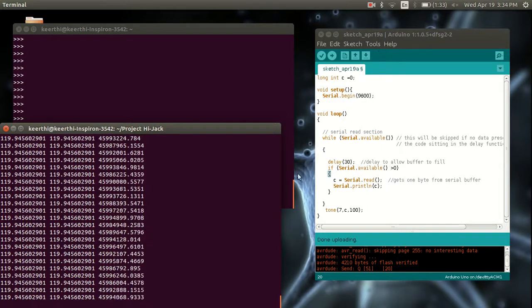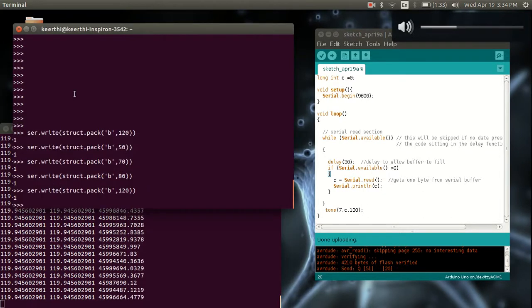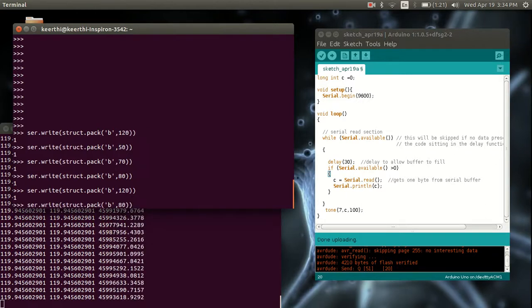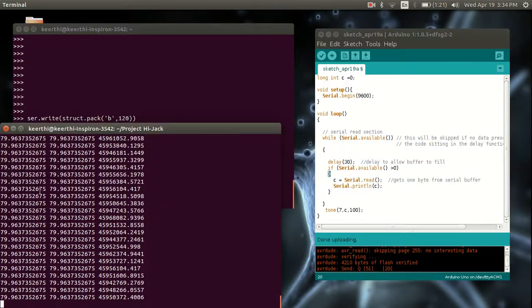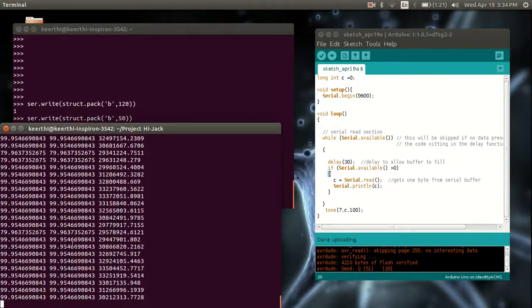Okay, I just paused to open up the FFT app, and you can see that this is printing out 119.95. It's just 120 Hz, so it is giving out 120 Hz. Now say you want to change it, you want to go to 80, and if you want to set that, just click on that and then bam, changed to 80 Hz. Now 90, if you want to give 90, just change this value. The FFT goes a little bit haywire, but okay.